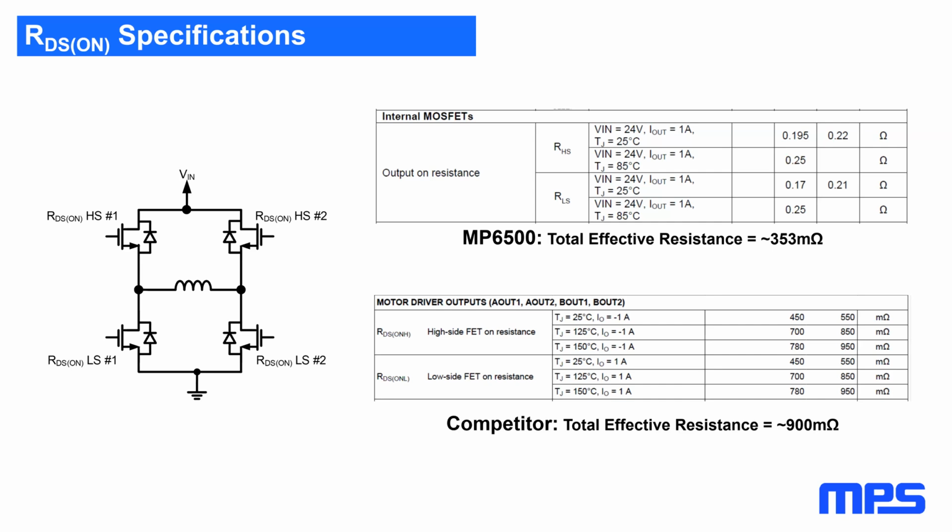During current regulation, most controllers will hold one leg of the H-bridge low and PWM the other leg. During PWM, the duty cycle varies. It depends on the supply voltage, current regulation set point, and motor speed, which drives the back EMF, which subtracts from the supply voltage. The duty cycle can theoretically vary between 0% with only the low side on and 100% with only the high side on. But in reality, most of the time, the duty cycle varies around 50%.